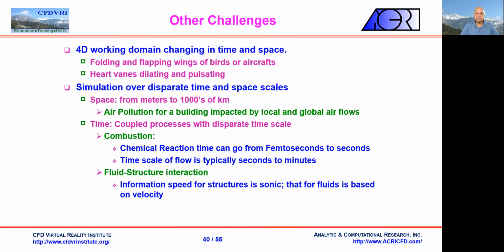Then there are processes which couple with disparate timescales. For example, take combustion. The reaction rate for one reaction can be femtoseconds, and another reaction may be at the level of seconds or sometimes even hours. The time scale for combustion is in seconds, femtoseconds, or milliseconds, and that for the flow is in minutes. In fluid structure interaction, the information speed for the structures is sonic. That for the fluids is based on its velocity. So which one would be the norm? Which one would govern?